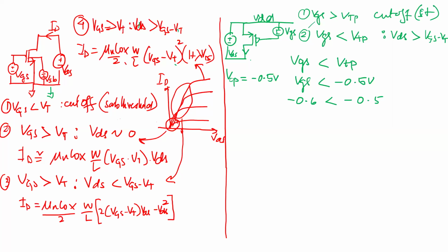When you're reading literature, typically they'll never use magnitudes, just to keep it clean, whether you're reading papers or textbooks. So that's why it's good to know this. But when I do my own calculations, even today, I just do VGS greater than VTP, VDS greater than VDSAT and all that. In my head, I know that it is all flipped. But if you have to write a paper or a document, then you have to be very clean. I've seen people write papers with magnitudes too, but just be aware of that.